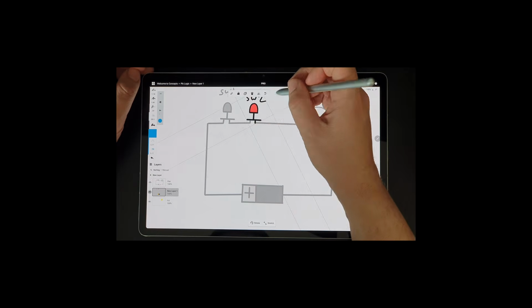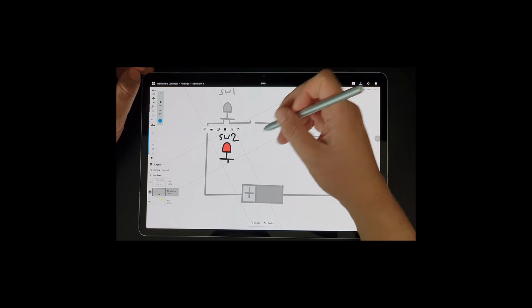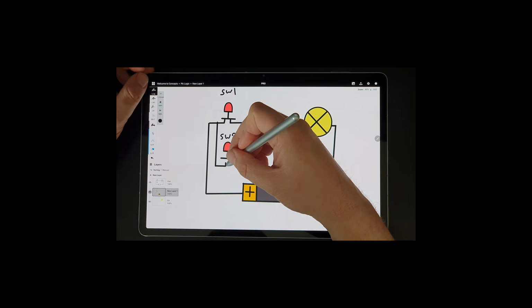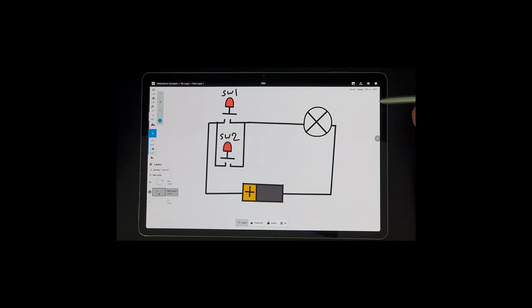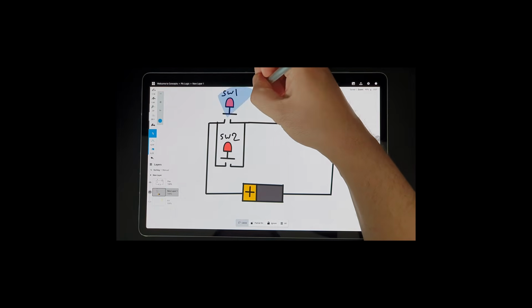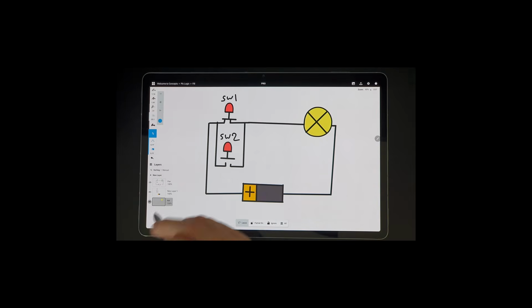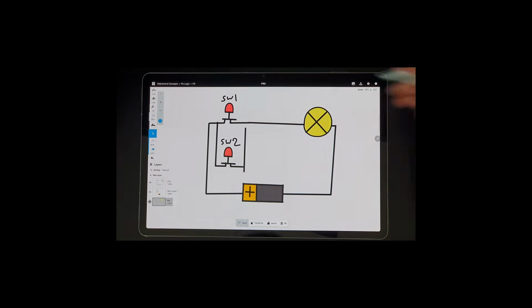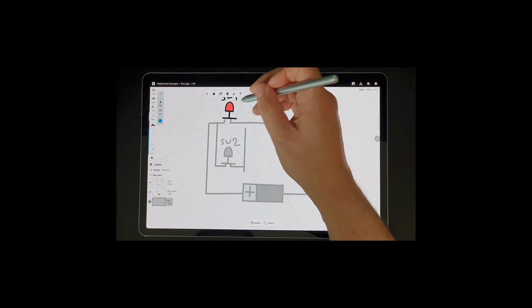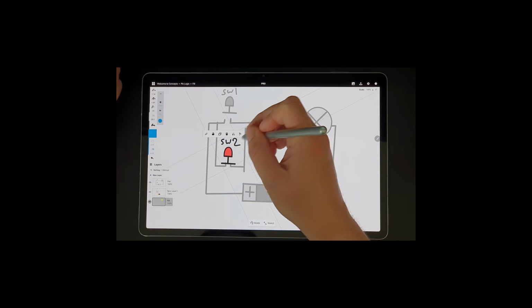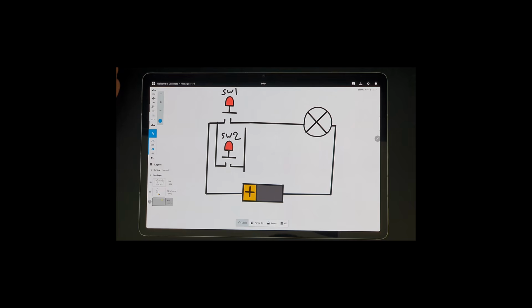Now let's suppose instead of wanting both switches pressed for the LED to be on, we want our LED to illuminate from either switch. To do this, we would have to change the configuration of the wiring. In our new OR configuration, when we close switch 1, the LED illuminates. If we close both switches, the LED remains illuminated. As you can see, only when both switches are open is the LED off. This is OR logic. Let's quickly draw the logic table for the OR configuration.